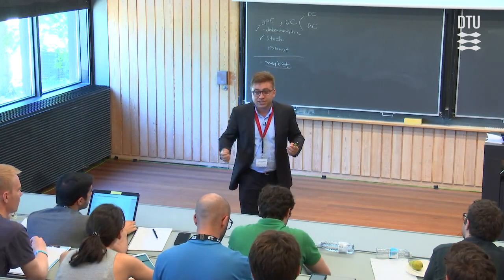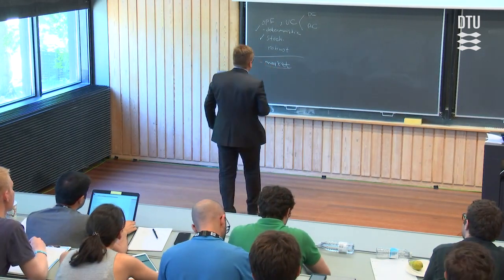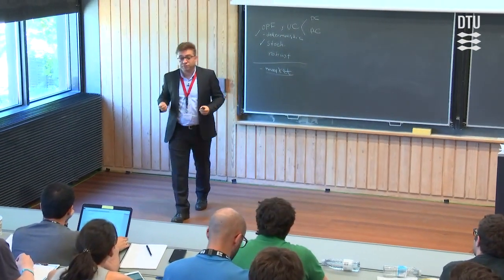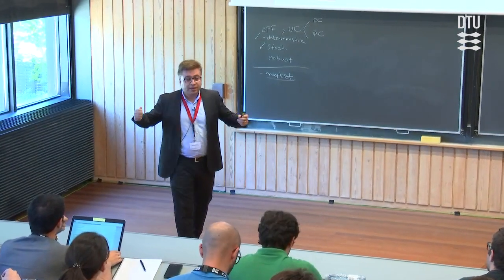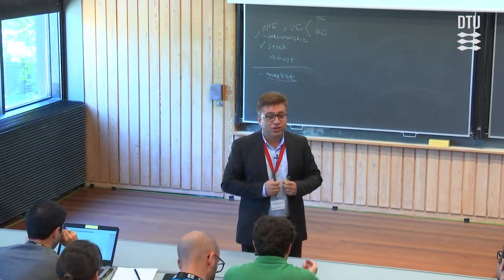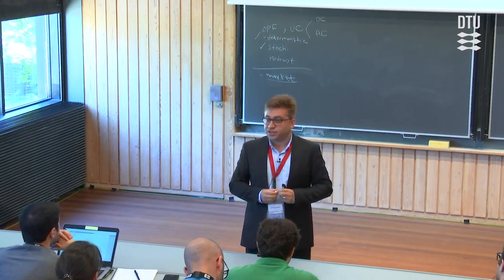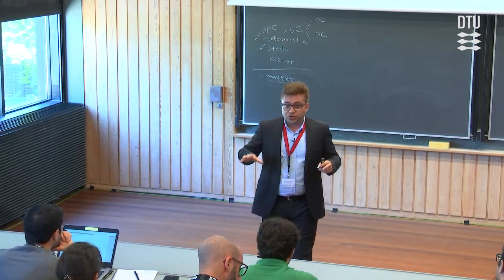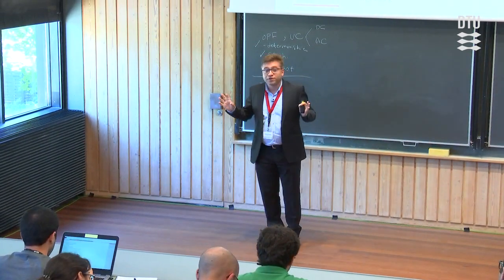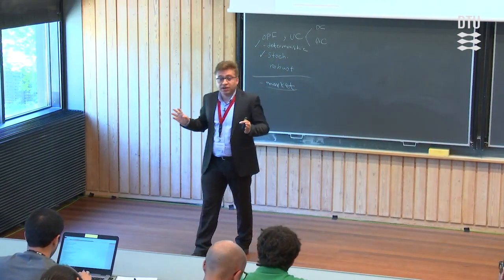But what we do in Europe, we don't solve the unit commitment problem. We solve an OPF problem, and we assume that the offers of the generators embody the unit commitment constraints of the generators. Okay? So in Europe, what we solve is an OPF problem without unit commitment constraints.